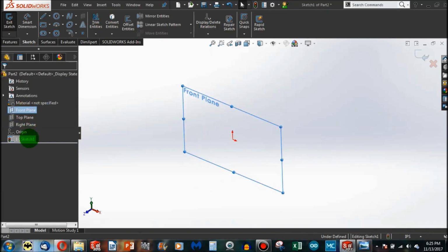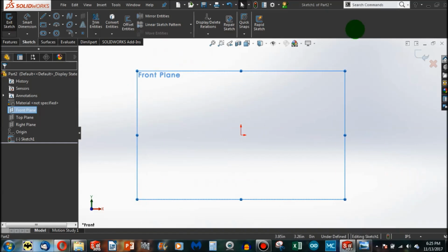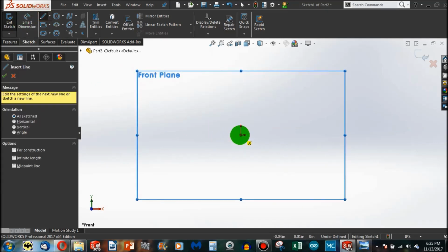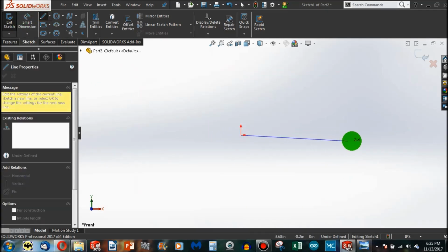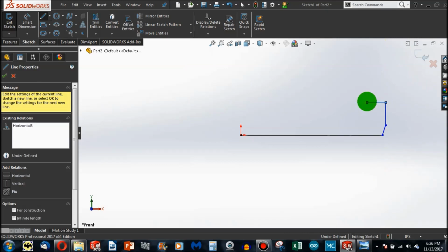And that's very significant on using the origin. Again, I push Control 8 to get that front plane, what we say normal to me, or on that straight-on view. When we use the origin, it will be very significant in the next video. So I'm going to make a horizontal line. This will be the bottom of our tape holder. I'll make another line. This is just free form, completely unconstrained, thinking that maybe this will look a little bit like what our tape looks like.